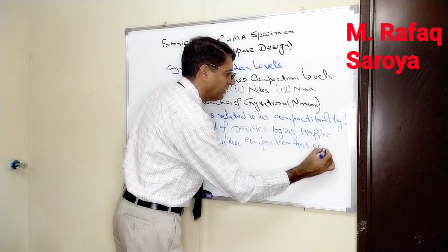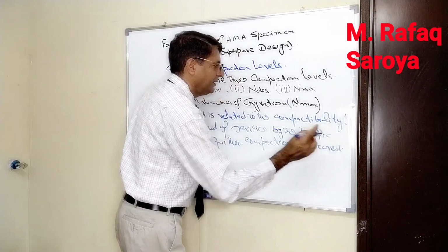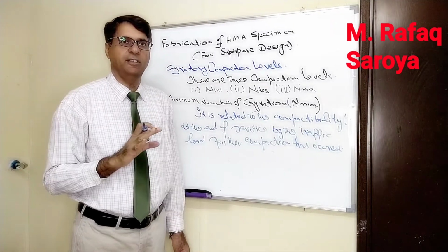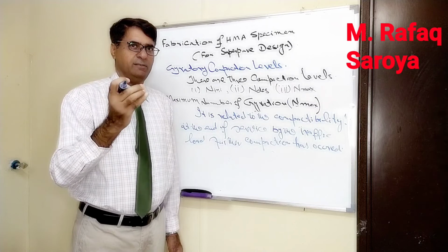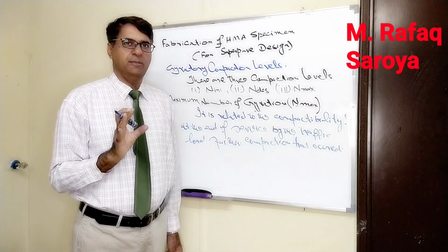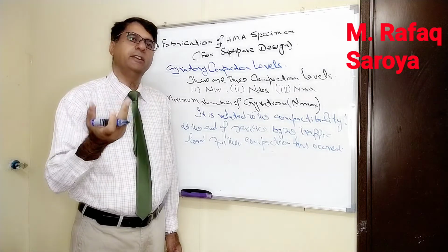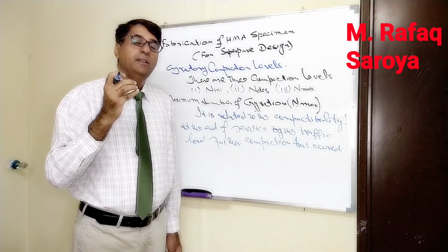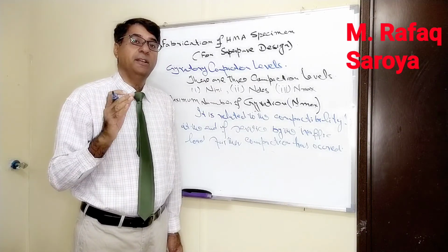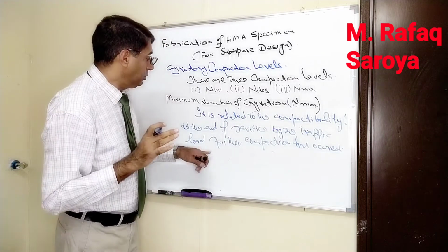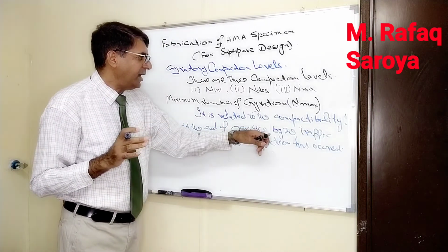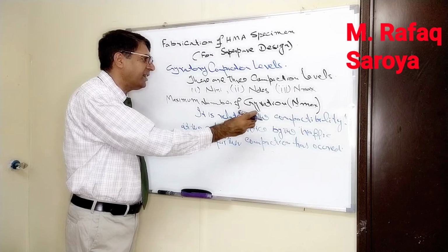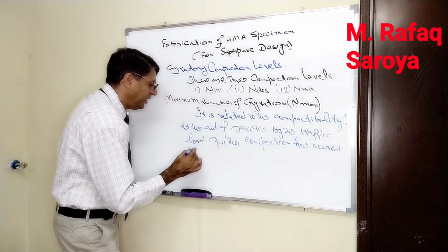Let me tell you the meaning of this one. When we say the end of the service life, for example, I have designed one road, constructed the road, and laid the asphalt surface, and in the initial stage we have a certain level of compaction. Now, under heavier traffic and under weather conditions, further densification is occurring because of the traffic load. Okay? Further compaction has occurred. This is represented by this number.